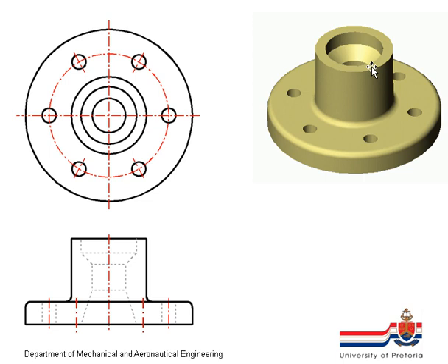This is just an example of a slightly more complex component. Big center line for this big circle. Then what we can do is we can make a single bent center line through all of the small circles to show that they are all on the same distance from the center, almost on the same radius, if you will. We can also show a radial center line through them to show the center of the arc to which all of them find the same distance.